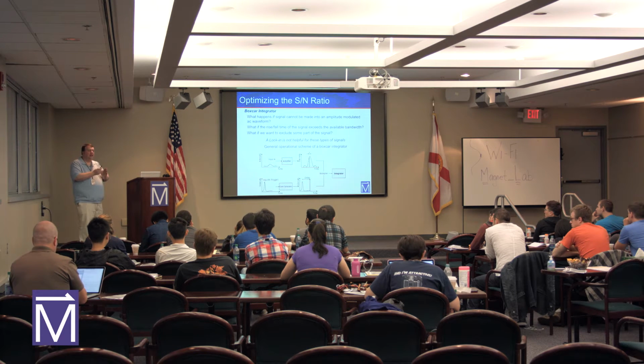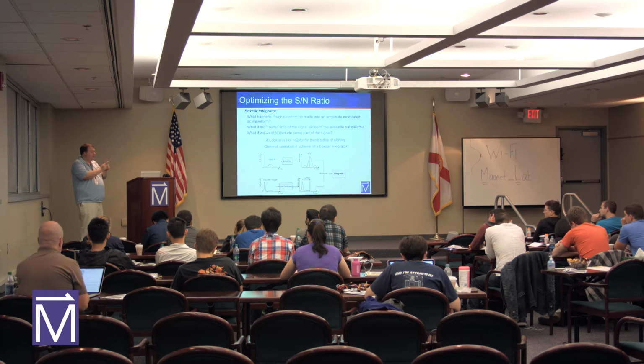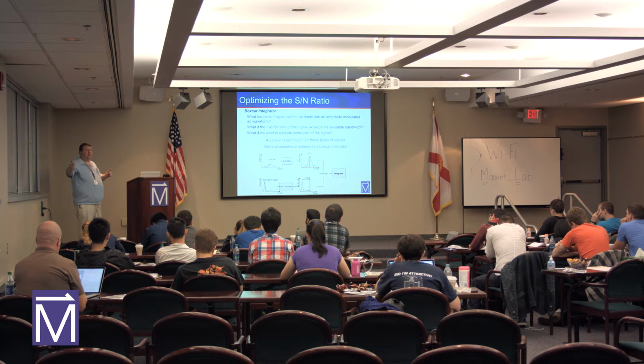When you're using a lock-in, you're looking for something that's periodic, and the pulsed laser meets that requirement, but the duration of the pulse in your detector is maybe a hundredth of the total period. So for instance, if it's 1 millisecond, you're operating at 1 kilohertz, and you're averaging a lot of zero signal in. So the amplitude in the lock-in can be quite small.